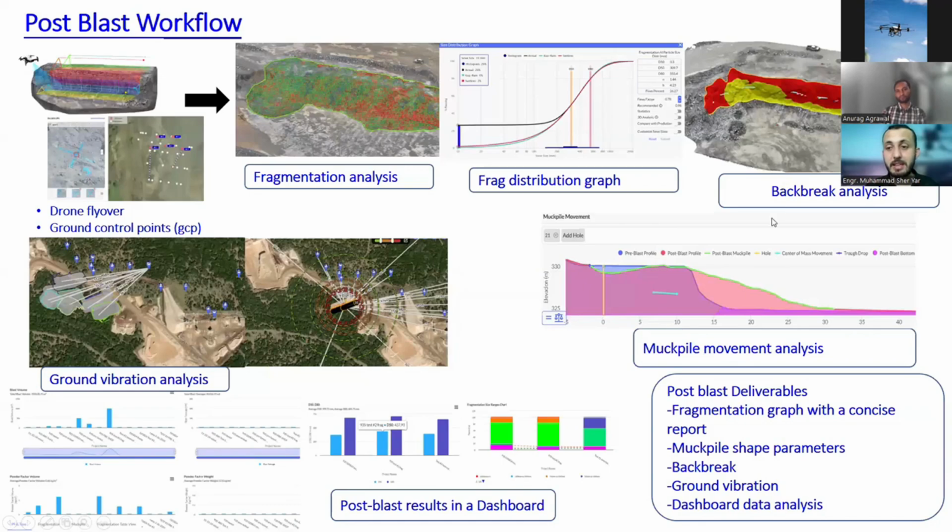do the analysis of back break. This means the area which you have planned to blast for the blast design which you have planned. So how much area you have covered more, or how much area you have covered less comparatively to the planned one. So this can be analyzed through this type of back break analysis.